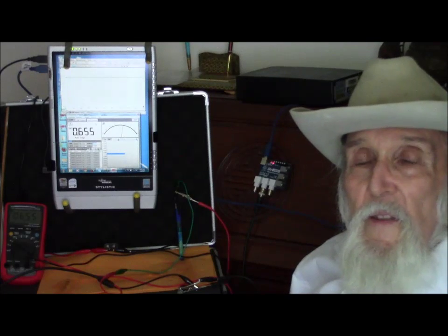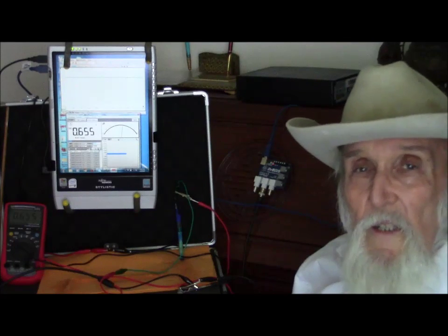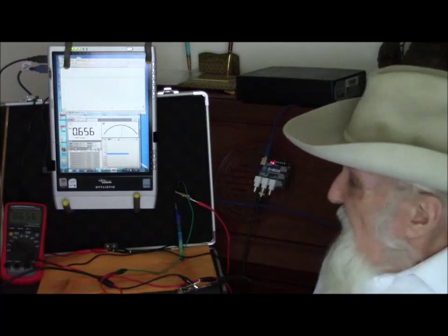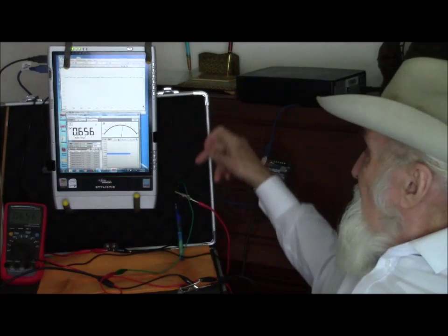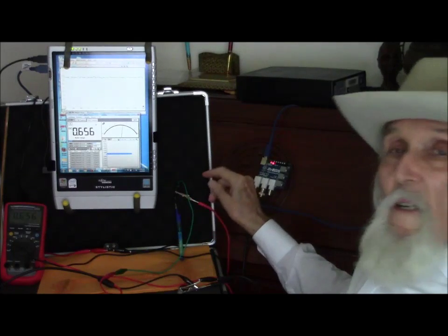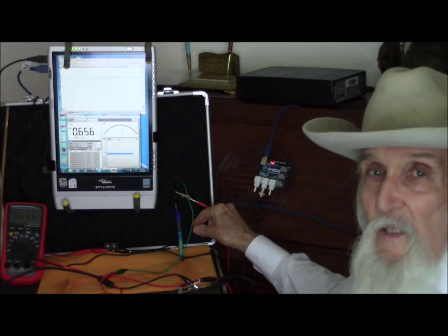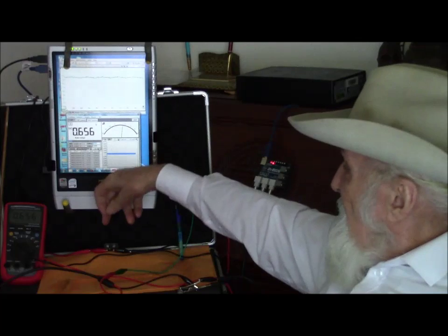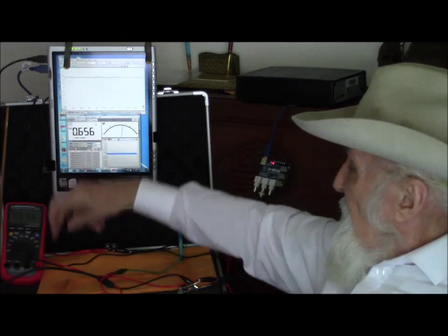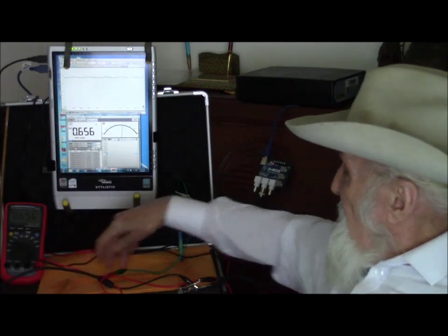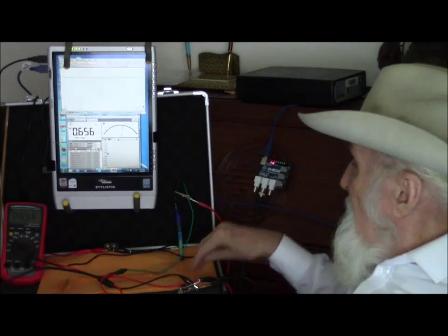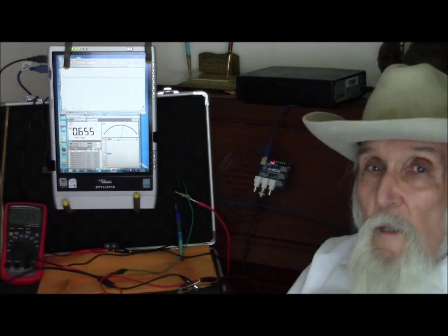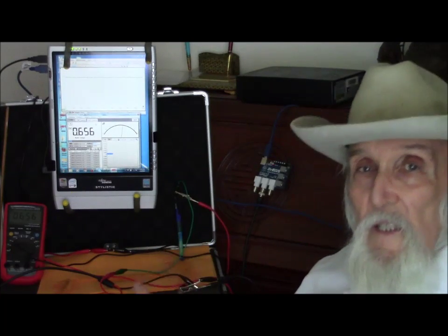Now, this is not the corrosion circuit. The corrosion circuit does not include the copper sulfate ground contact electrode. The corrosion circuit is from the battery to this nail, through the electrolyte, to that nail, and directly back to the battery. That is not what we are measuring with this procedure.